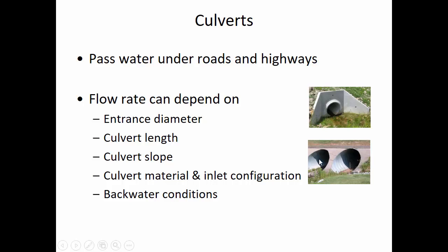or you can see here's a multi-barrel culvert, whether you need one versus two, depends on a lot of different factors, like the entrance condition. You'll notice that this has some wing walls on the side of the barrel, and those wing walls affect the flow capacity of the pipe itself. If it was just a pipe sticking out, it wouldn't be able to carry as much as if we have these wing walls kind of guiding the flow into the pipe. And we're able to account for that sort of flow settling effect as the water approaches the culvert.